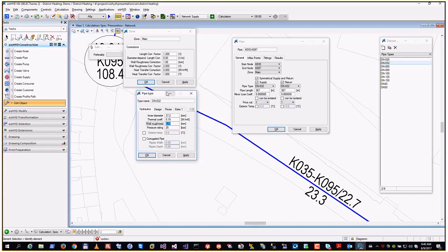It's not going down. If you change the equation, mass flow is the load divided by Cp times delta t. So if the delta t is higher, it's lower mass flow. And when you include the heat loss, you will find then higher mass flow and higher pressure losses.